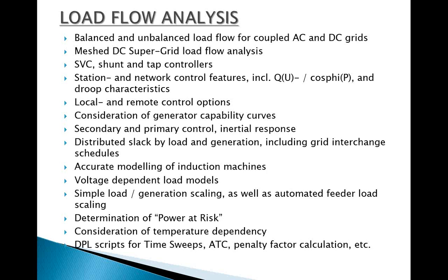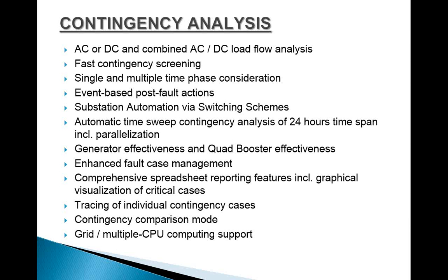Now it's contingency analysis. AC and DC and combined AC-DC load flow analysis related to contingency cases can be conducted. Fast contingency screenings are there. Single and multiple time phase considerations. Event-based post-fault actions can be conducted. Substation automation via switching schemes can be done. Automatic time shift contingency analysis for a 24-hour time span, including parallelization.